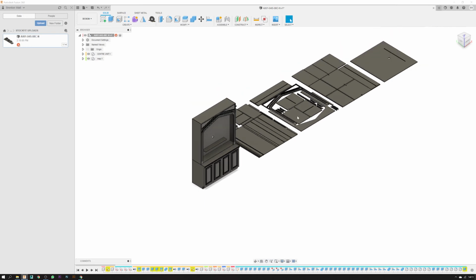You'll just have to notice that the flat packing is done referring to this actual file, so it could cause a couple of hiccups if you just machine the G code as supplied. But I'm sure if you understand how to flat pack and to set up paths and so on, it's not a problem. Then you can just alter this model and do your own.